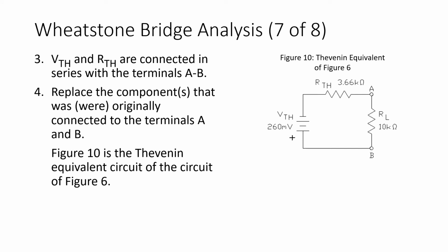So we then place V Thevenin and R Thevenin in series with the terminals A and B and connect the component or components that were originally connected to those terminals. Figure 10 shows us the Thevenin equivalent circuit of the circuit of figure 6, again with respect to terminals A and B, or as seen by RL.